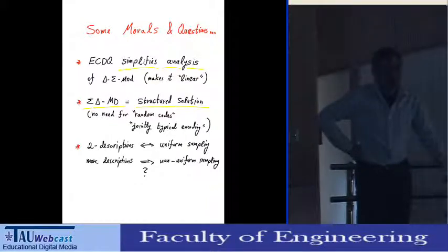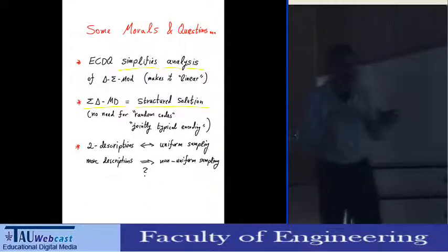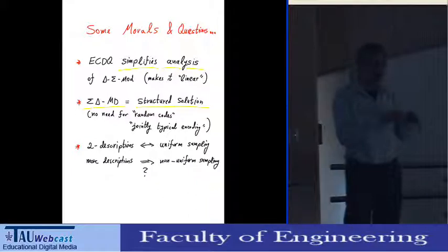By the way, something I want to mention, if there is not any other question: sigma-delta modulation is known as a hard problem because of the nonlinearity of the quantizer. And people didn't try to go beyond the first order prediction, because it becomes even more complicated and there are issues of stability. But with the dithering, everything is nice.